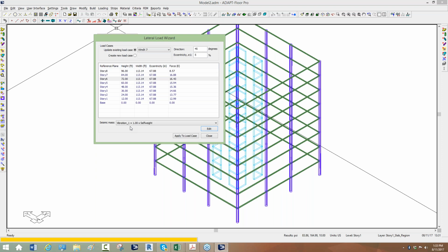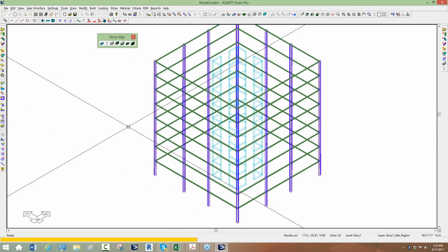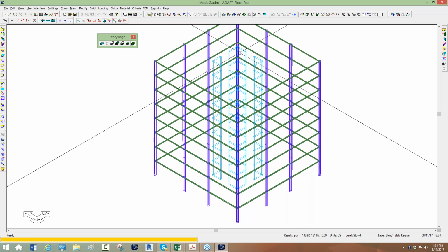nodes. And so when we solve these load cases, we first have to know what the node numbers are, what the frame numbers are, and that happens when you press analyze. At that immediate point, the program numbers all the frames, numbers all the shells, and then it can assign these nodal forces to those particular elements. So if you apply these load cases and I say close, nothing appears to happen because we don't see all these loads externally applied on the building, and that's again because of how we solve those load cases.